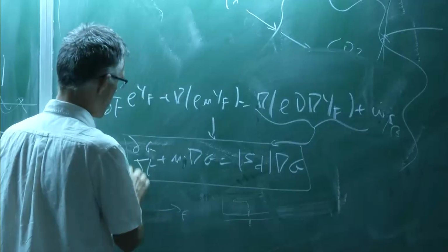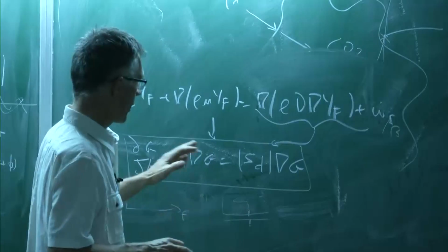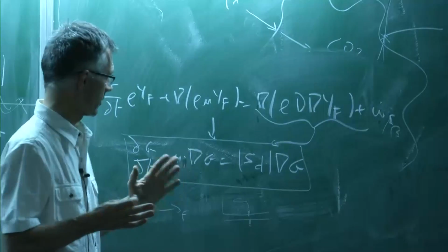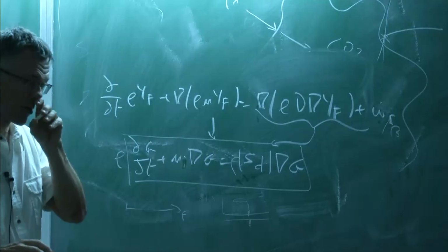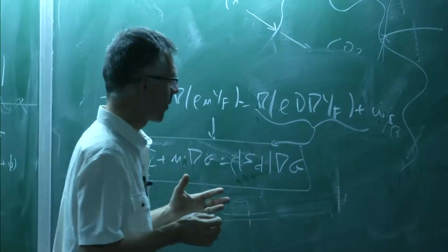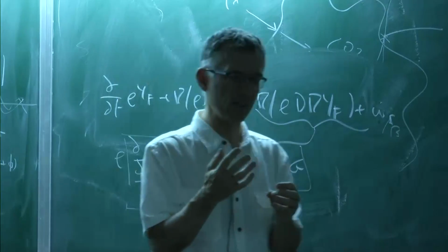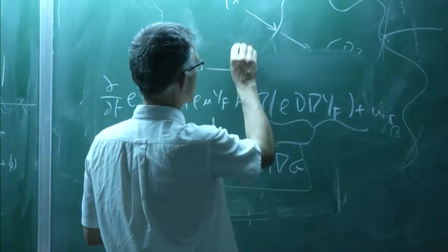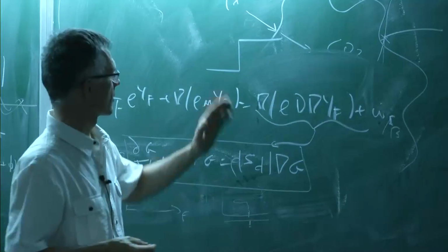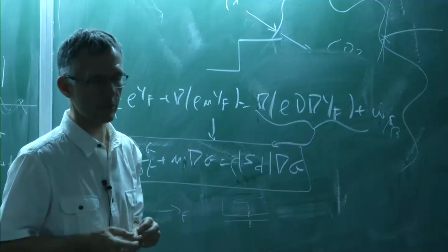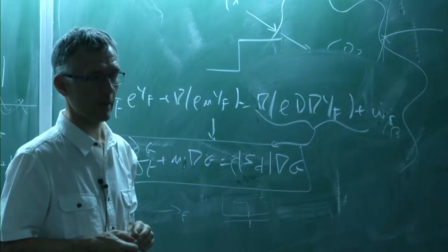And the main problem with the G equation is really to handle the variable density. If you do a constant density flame, you're fine. The problem with the G equation is that if the density is changing, you are in trouble. People who try to use the G equation always get into problems to reconstruct the density field. Because in the equations, it's easy to say that density is a step function. But as everyone knows in this room, if you do CFD, you cannot do that. You need to find a way to handle an infinitely steep gradient, and that's difficult for density. That's the main problem.